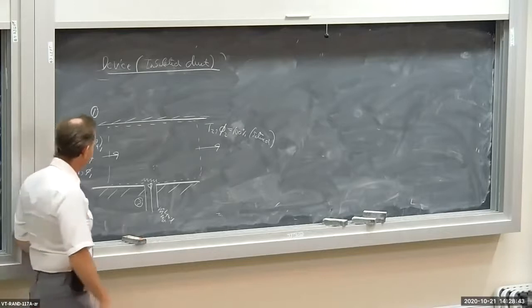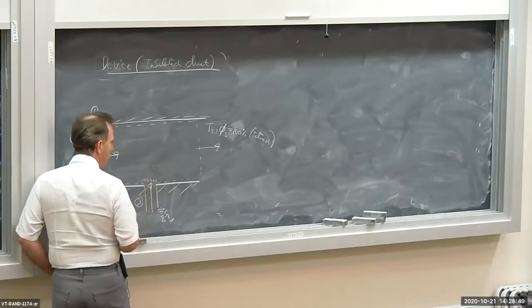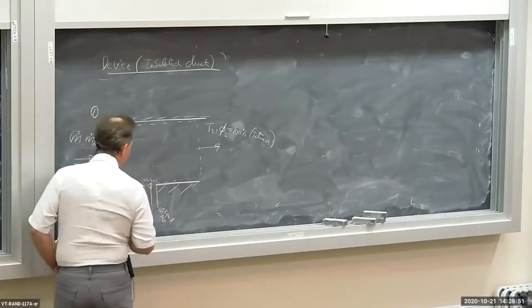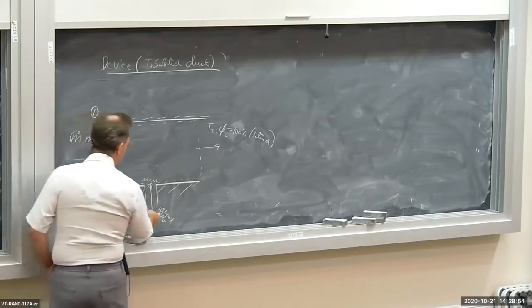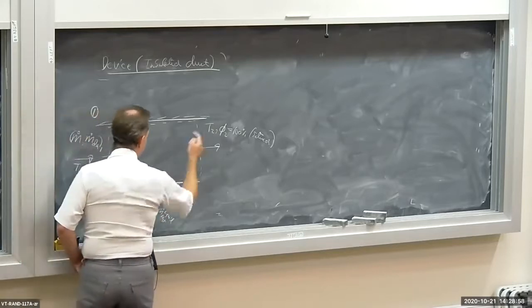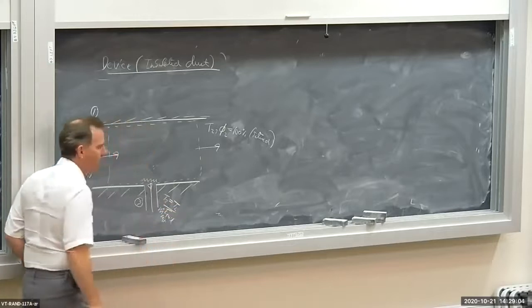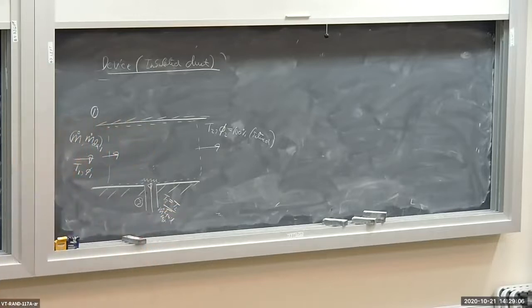Now, by the way, a little constraint here. I'm going to constrain the mass flow of the liquid, which eventually evaporates in the duct to humidify the air. I'm going to constrain the temperature here for the inflow of liquid to be equal to the outflow temperature. So I'm going to say here that T3 is equal to T2. I'm going to underline that. The temperature of the injected liquid is equal to the outlet moist air temperature, okay?